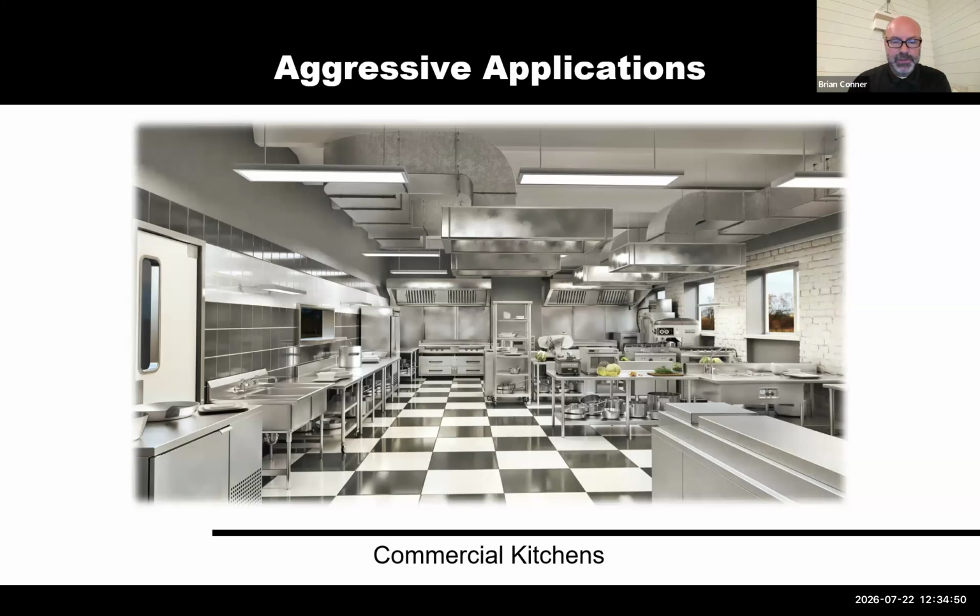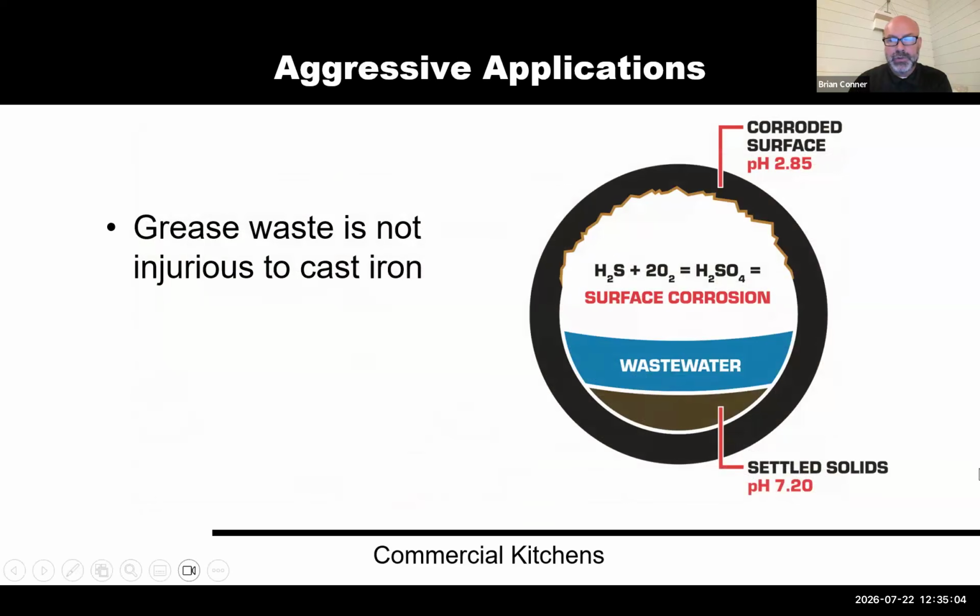And if you guys showed me somebody who was cleaning out their grease interceptor on a normal basis, it'd be the first one that I saw. So with those solids that are left behind, they off gas as well, and it's a real problem because it creates hydrogen sulfide gas. Hydrogen sulfide gas from the waste that is settling at the bottom of your piping.